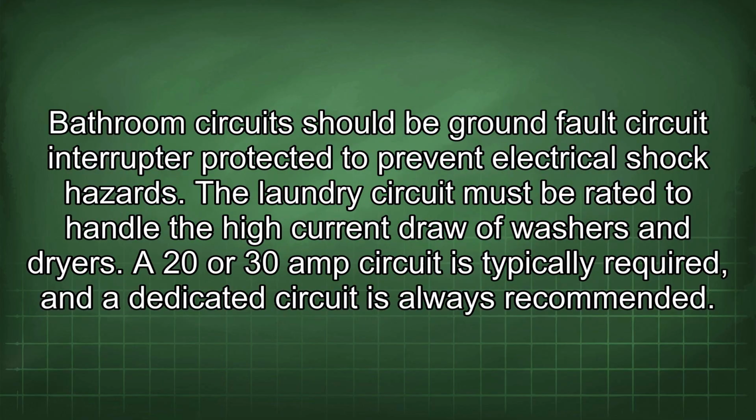The bathroom circuit should be ground fault circuit interrupter protected to prevent electrical shock hazards. The laundry circuit must be rated to handle the high current draw of washers and dryers. A 20 or 30 amp circuit is typically required, and a dedicated circuit is always recommended.